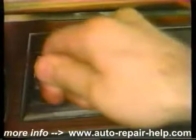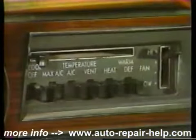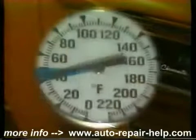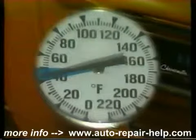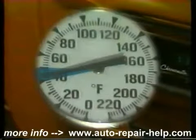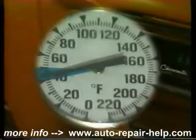End your test in the AC maximum mode and with the temperature control in the cold position. Place a thermometer in the right center vent. If the system is operating normally, the temperature at the vent will be 40 to 45 degrees Fahrenheit, provided the ambient temperature is 70 degrees Fahrenheit and the humidity is relatively low.